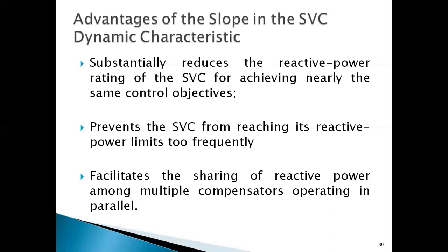That is one advantage. And as it reduces the reactive power rating, now reactive power will be reserved, because of which sharing of reactive power among the multiple compensators operating in parallel is also possible. These are the three major advantages for this.